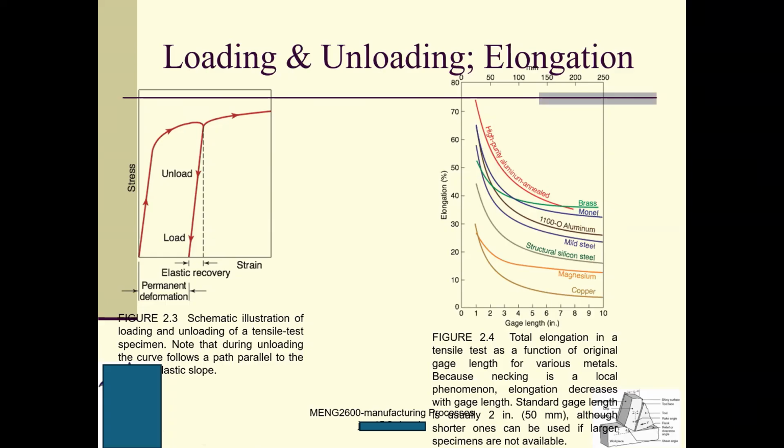Questions, guys? So you said that from plastic deformation you get work hardening. Is it after plastic deformation? Yes. Here is my initial yield strength, right? So if I have plastic deformation, this one will be my new yield strength. This new yield strength is usually higher than the initial yield strength. The difference between these two yield strength values is called the strain hardening or work hardening.